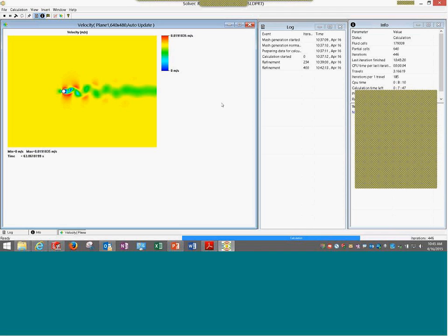So I would refrain from saying yes we can do it or no we cannot, but as I said yesterday, at least what I heard is that 80% of the commercially used profiles can be handled using the K epsilon model. But saying that, I also know that there are a few more specialized turbulence models which handle more intricate profiles. Rather, there are softwares which can actually do the simulation for those kinds of aerofoils.